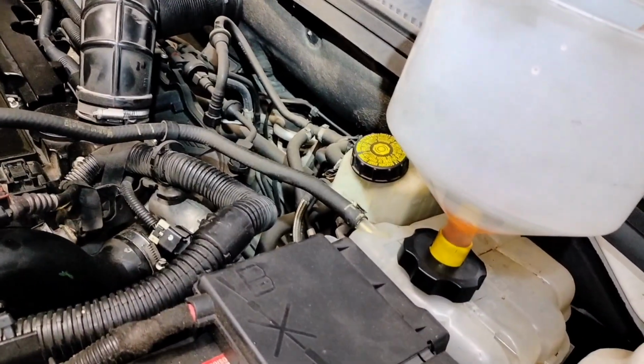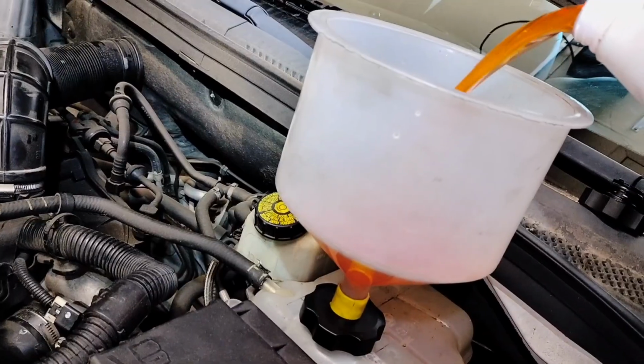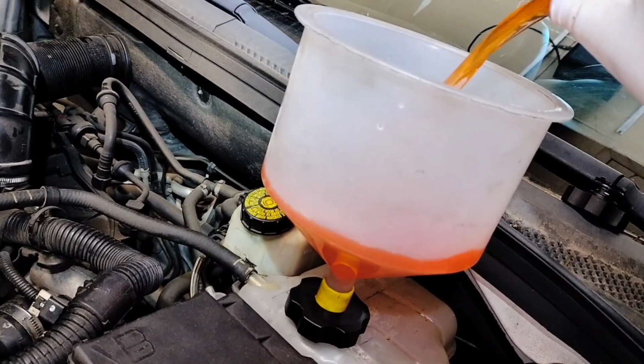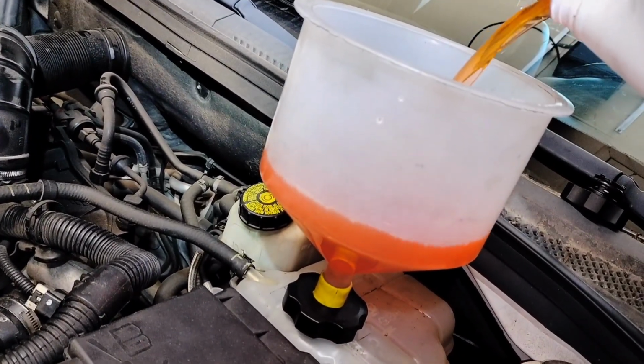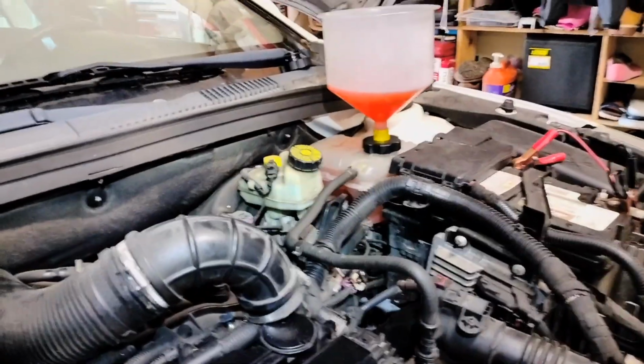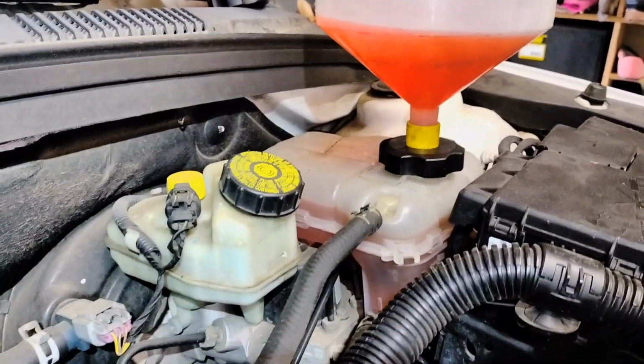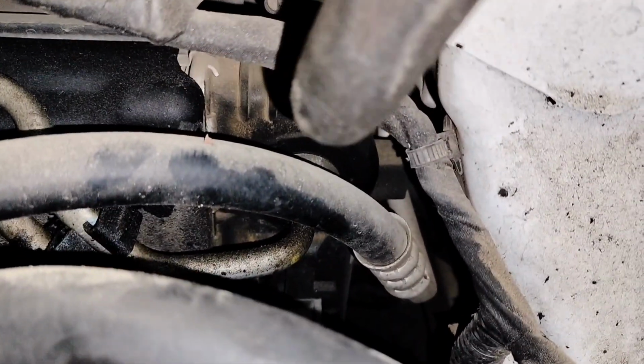The vehicle's off, engine off. I'm adding the coolant that I drained out from the vehicle, so I know it's gonna be enough. And there's a point where the coolant won't go down anymore. In this case, I know that the coolant should go all the way down because that's what I removed from the vehicle. At that point, that's when we want to open that bleeder right there on the radiator.